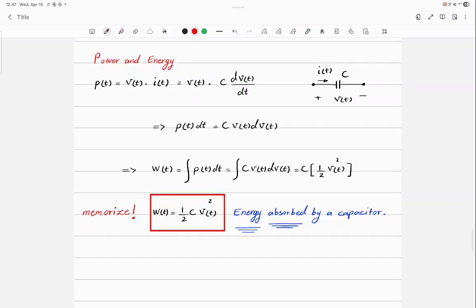How did you combine inductors when they were in series? You combine them like you do with resistors in series, right? Now, how do you combine capacitors in series? You combine them like you do with resistors in parallel. You see? The opposite of it.